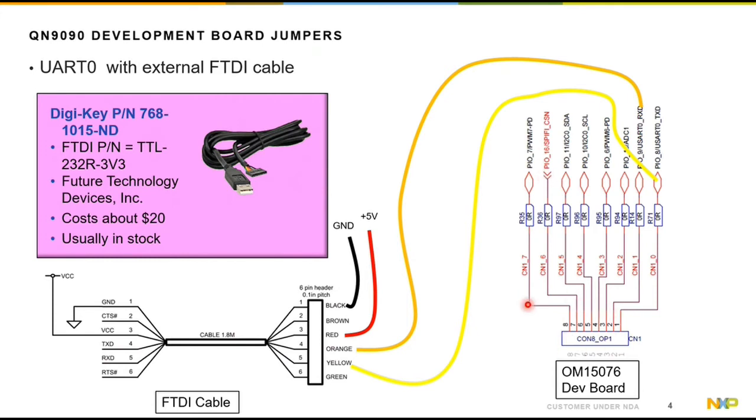If your board is self-powered, then you would leave this hanging off, but you would want to take your ground. I should have drawn on there. You'd want to take your ground and go to a header on the board because you don't know what these are. These are floating. If your laptop, especially if it's running off of a battery, that port will be isolated and will be floating. So the minimum 3 wires will be transmit, receive, and ground.